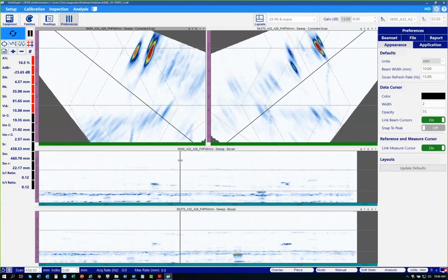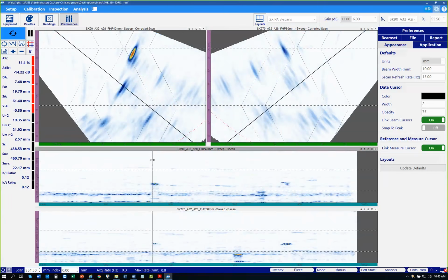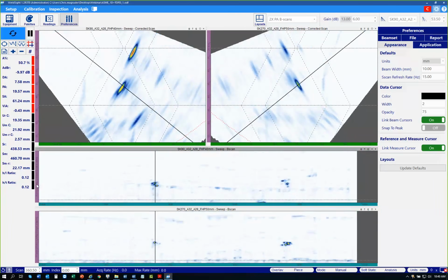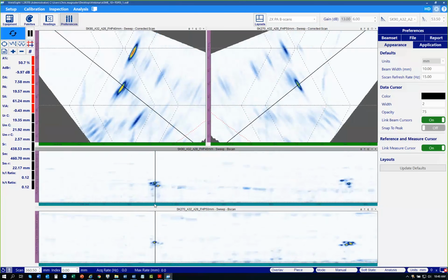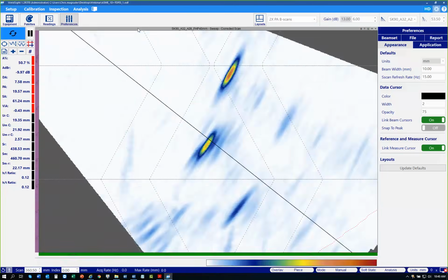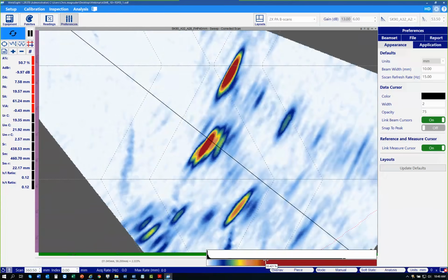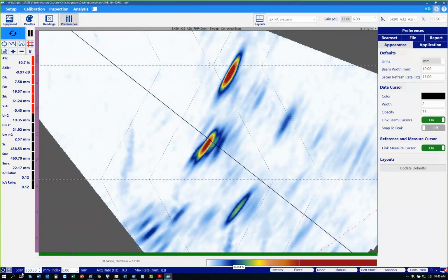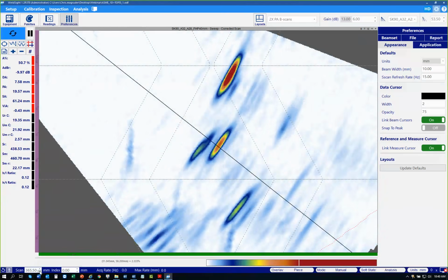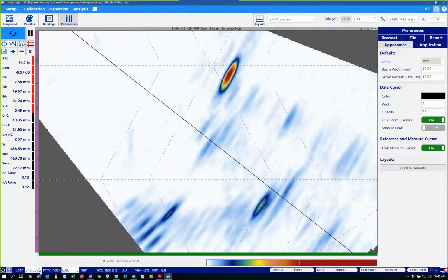So if I look at the middle of the weld here, we have a porosity indication here. I'm going to zoom on the UT ruler. I'm going to zoom on the scan axis ruler and reposition it slightly so we can see these two. And again, you saw me do it a couple times. If I double click and maximize the screen, we can see in color and exaggerate directly here. And again, these A32 probes at 5 megahertz are real detection champions for porosity and slag and these typical defects.